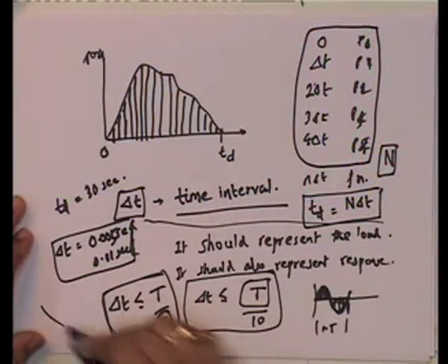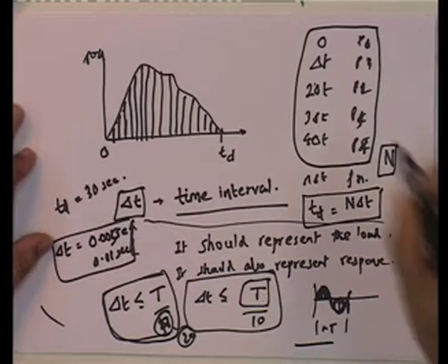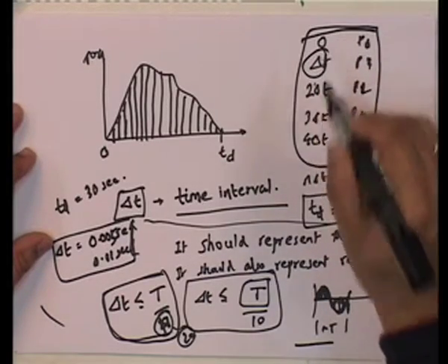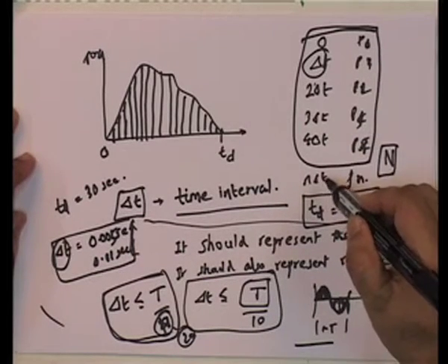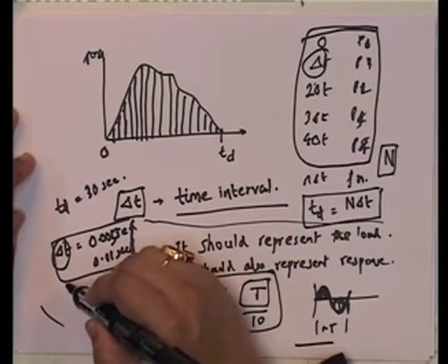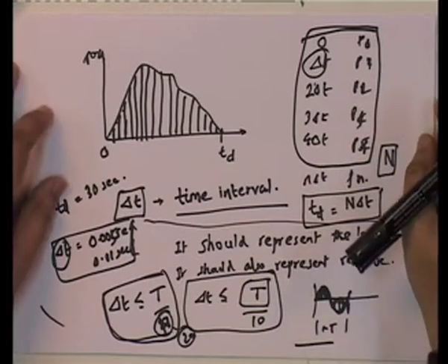We will show you when we go to the lab that there are some data acquisition systems that can do it at 1000 samples per second. In other words, delta t is measurable at 0.001. So, let us be very clear. What we are doing here is looking at, for the numerical analysis, this delta t, which may be different from this delta t, because this is more digitization. Now, if we digitize, how should we get this? Well, there are ways and means of doing it.